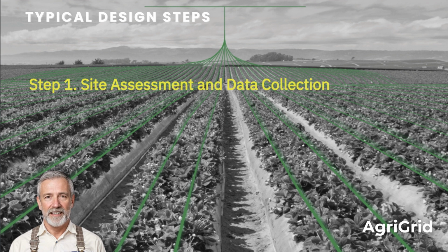This can be done by visiting the site to evaluate topography, soil type, and drainage patterns. The area is measured to determine shape and elevations and other physical characteristics like the water source. Water can be supplied from many sources such as a well, channel, river, dam, or municipal supply, and test its flow rate and pressure. Next, you will assess climate conditions, for instance, rainfall, temperature, and evaporation rates. With this information, you can determine the types of plants or crops and their water requirements.